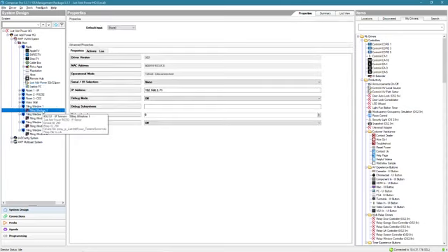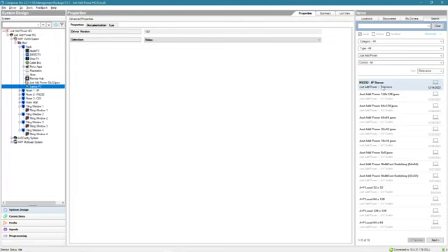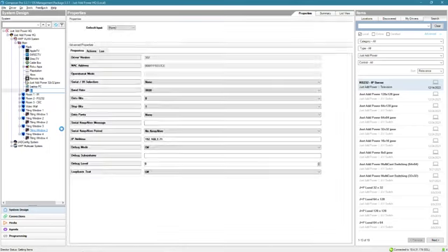We've also added 4 of the Just Add Power RS-232 IP server drivers. Those are going to act as the receivers, essentially the windows in the tiling transmitter. There are 4 windows in the tiling transmitter. But all those are just for HDMI connections, so we can actually switch sources on them. In order to do layout control, we have to add one more Just Add Power RS-232 IP server, and this is to control the tiling layout. We'll just go ahead and name it tiling layout control.